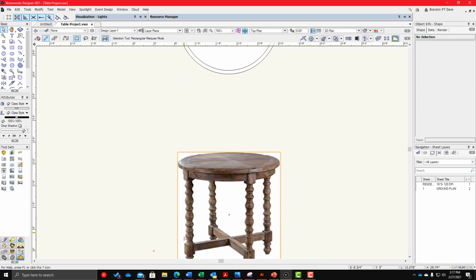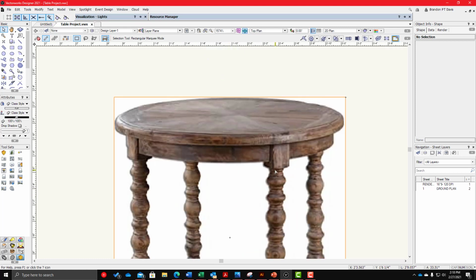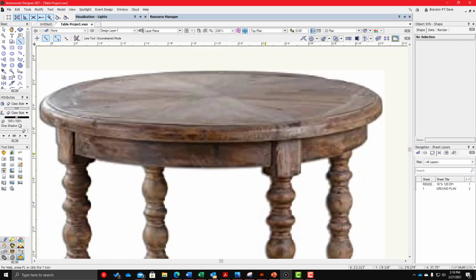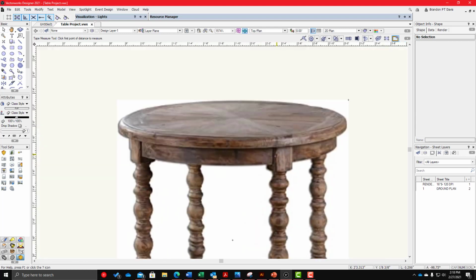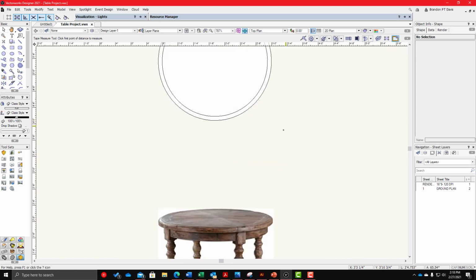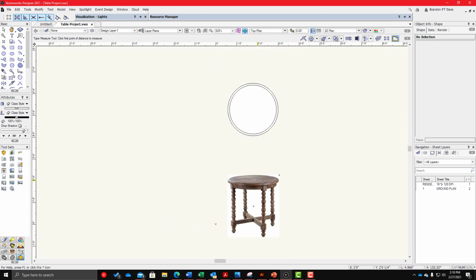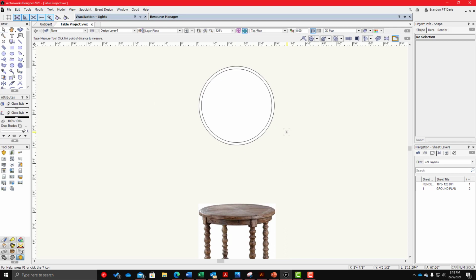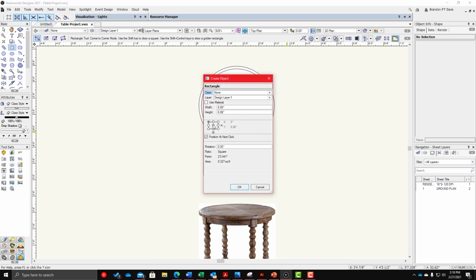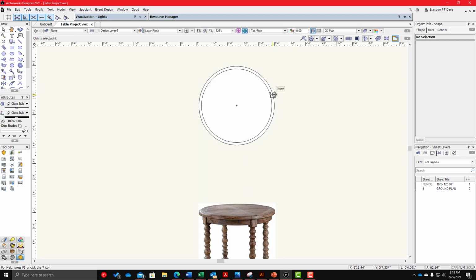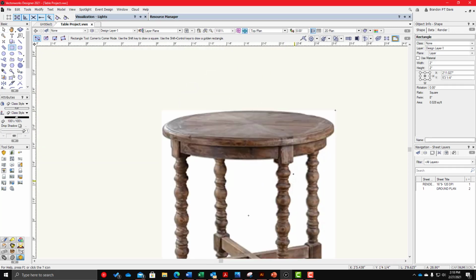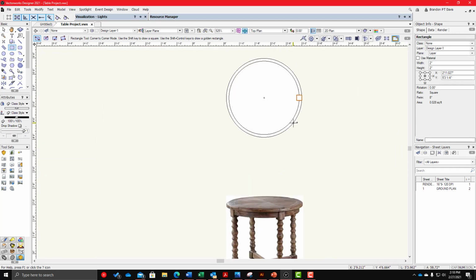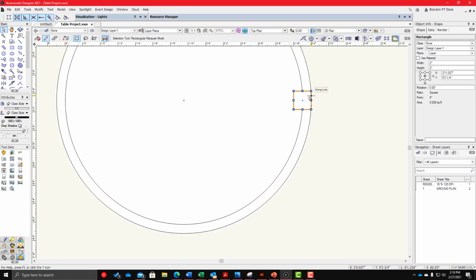And we have 4 legs. So you can take the tape measure tool, which is hotkey T. It says about 2 inches. So I think what I'm going to do is 2 inch for the sides. If I hit 4 twice, I can actually create the square relatively quickly. So from the center, it's about here. If I look at this, yeah, it looks about right. It looks like it's inset a little bit.